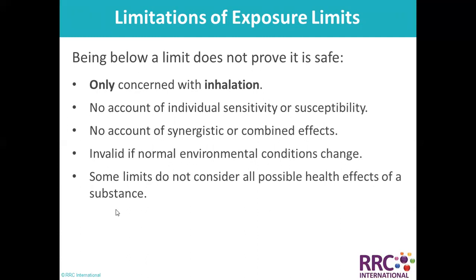Like one of the incidents, if I remember exactly, the persons were doing spray painting in a confined space, kind of a room, underground. They painted probably in one shift for 6 or 8 hours, and then the second shift guys came and they were having another job, and no gas testing was there, no PPE they used. They had no idea this confined space or this room was already occupied with toxic fumes, and maybe some toxic gases could also be there.